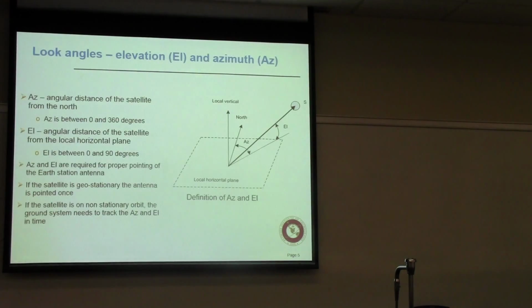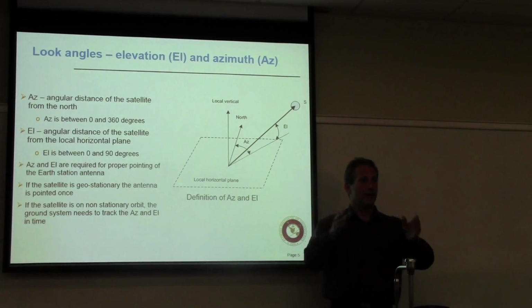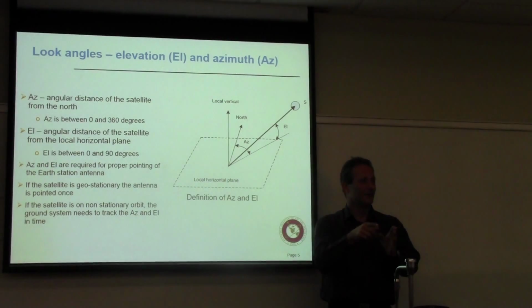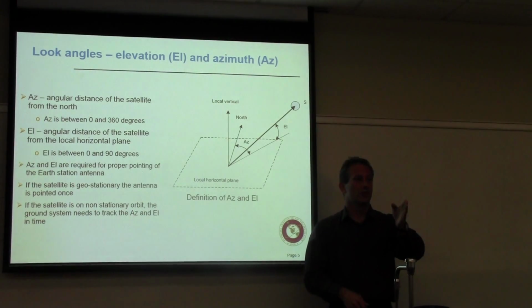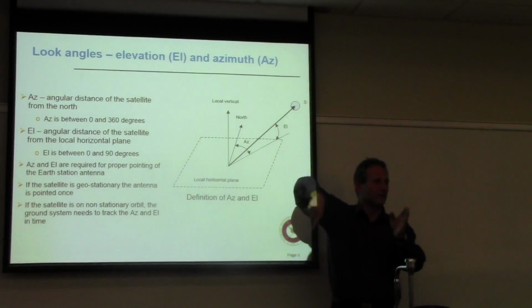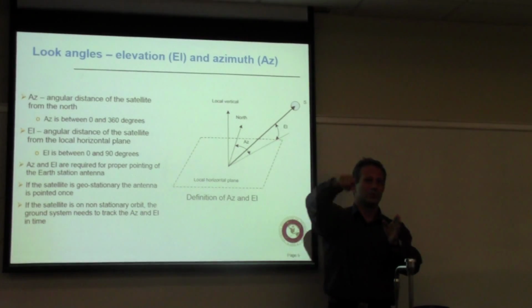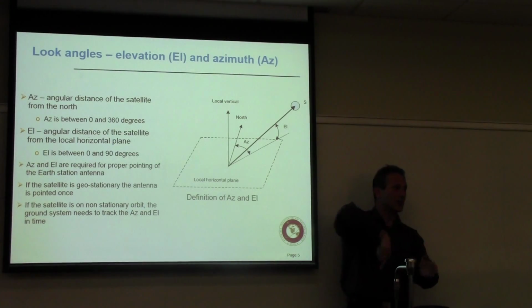Oh, one thing that is really a little bit messed up here. Unlike all the other angles, azimuth is calculated clockwise, right? So if I say azimuth is 0 degrees, that means pointing north. But if I say 90 degrees, where am I pointing? East, right? And that means your angle is calculated this way, as opposed to counterclockwise, where for almost every other angle, you calculate angles counterclockwise.